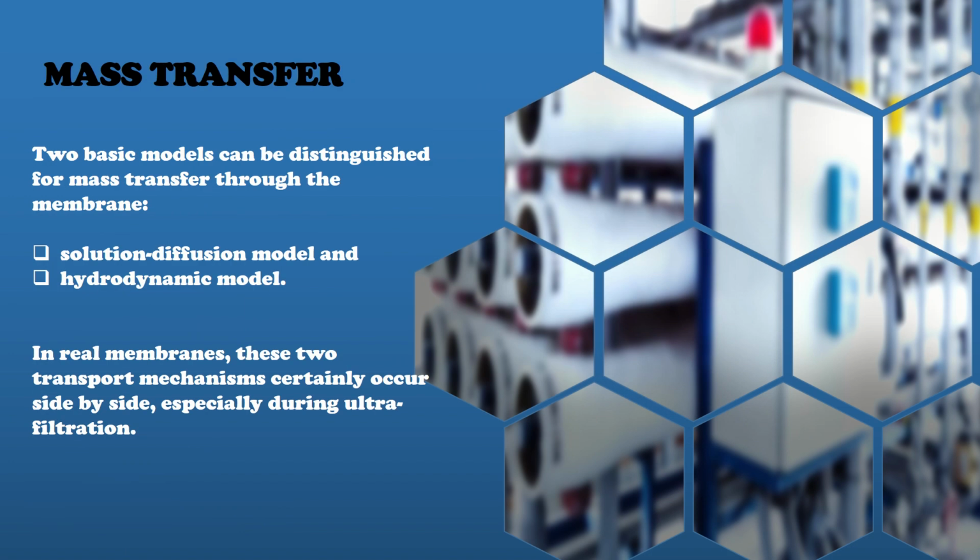Mass transfer. Two basic models can be distinguished for mass transfer through the membrane. The first one is the solution diffusion model and the second is the hydrodynamic model. In real membranes, these two transport mechanisms certainly occur side by side, especially during ultrafiltration.